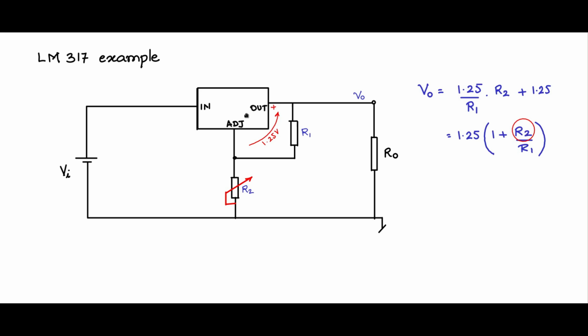Now, apart from this, there are a few other protection components that are needed to complete the circuit. First of all, of course, we need to put a 0.1 to 1 microfarad capacitor here. This is just in case, to make sure that there is decoupling at the input side and there is sinking capability also. Likewise, on the output side you put a capacitor of 10 to 20 microfarads.